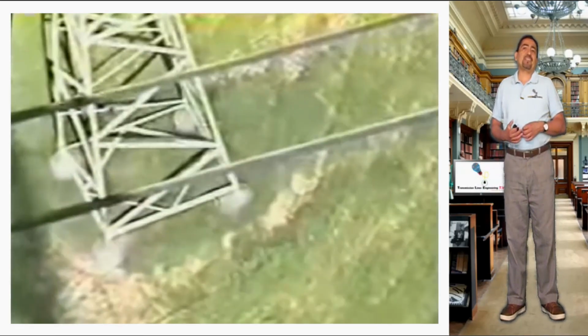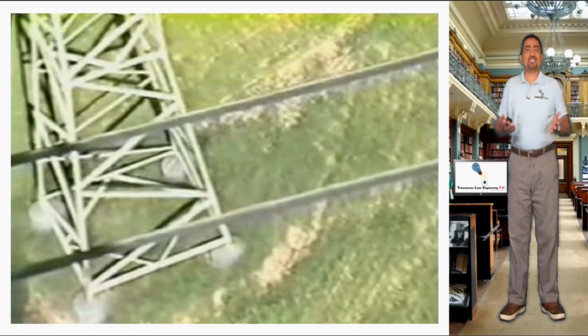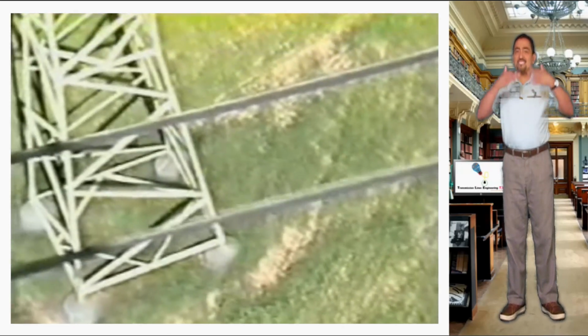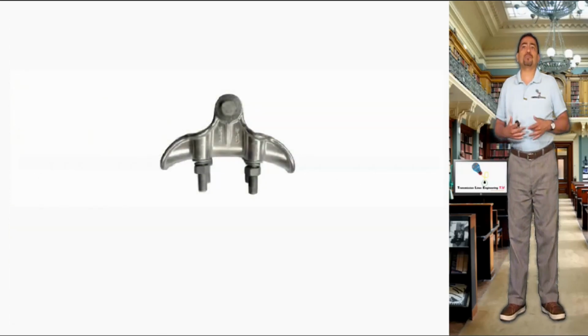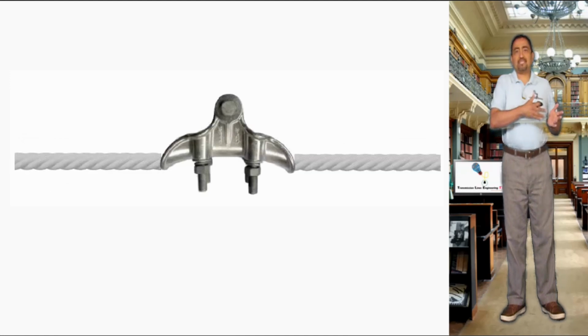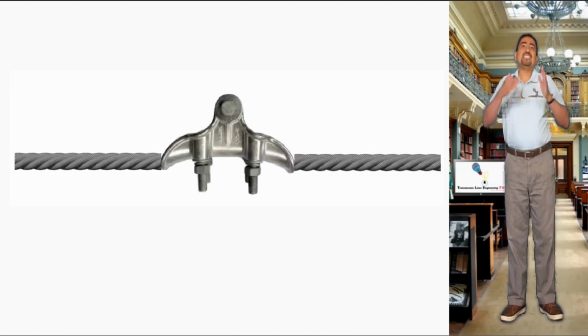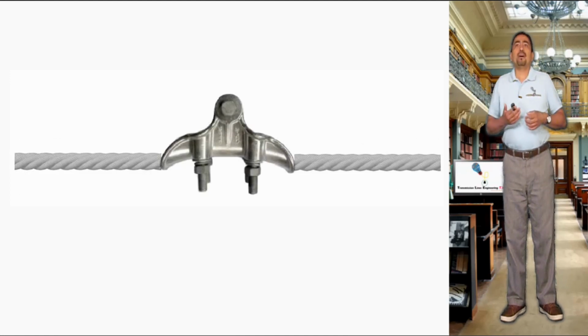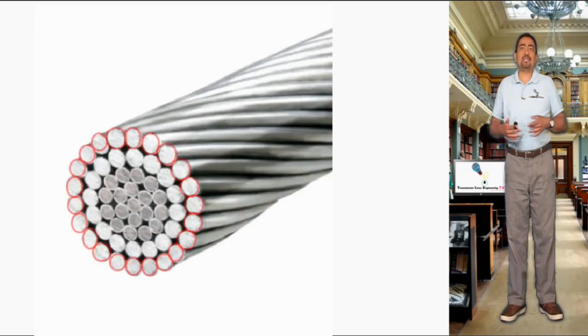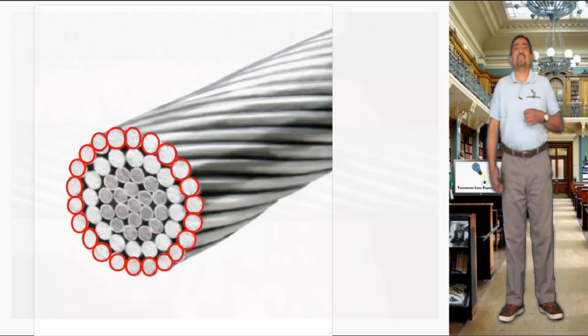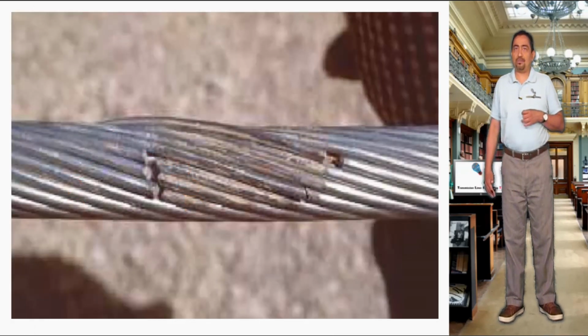This fatigue effect appears when the external wires of the conductor are permanently attached to the attachment clamps, so that the constant movement causes a weakening of the outer layers of the wire, resulting in the mechanical breakdown of the conductor.